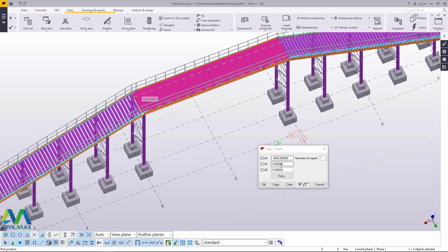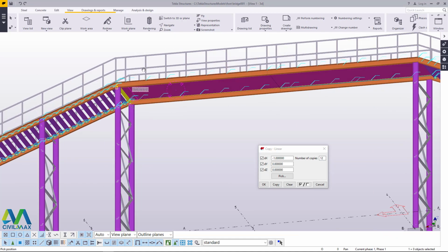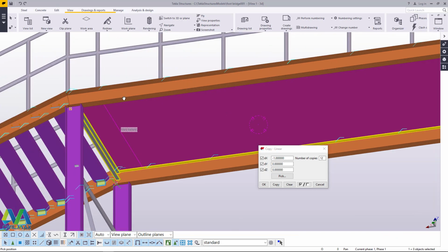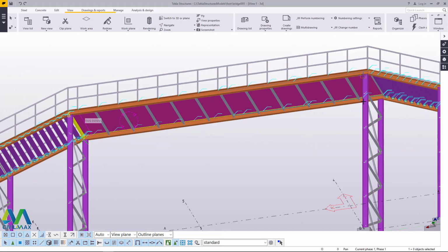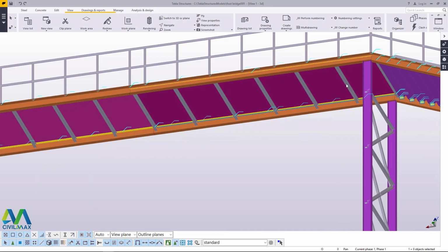What we did previously, and we'll change this to a meter, and we need 12 of these. And I'll come back here and rotate this so that when we invoke that copy command, we'll be able to see actually what is going on. Now when I come here, let me change this dimension to a meter, not 1 millimeter. That's very funny. Now I'll click that, and you'll be able to see this has been populated exactly to that far end. And don't worry about the connection.